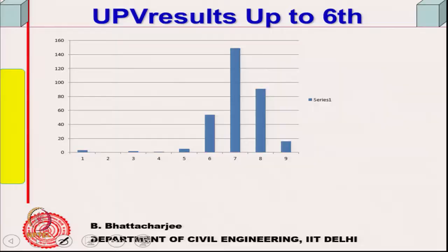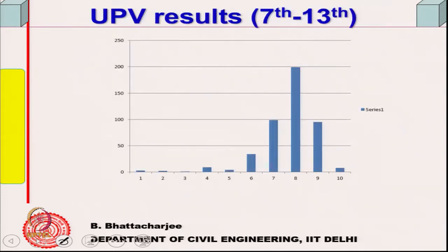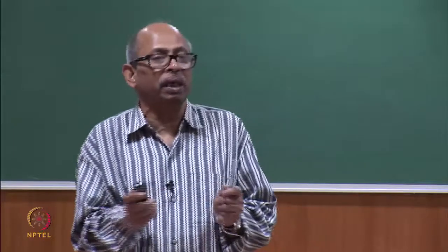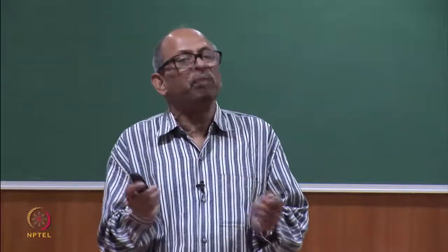So, you see this same up to the 6th floor, it was uniform concrete, but there is some bad concrete down there. So, it is skewed; there was some bad concrete, but not many. For floors 7 to 34 it was still increasing on this side, the ultrasonic pulse velocity result. I am plotting the histogram and this histogram did not match with each other. Initially when we plotted we found different peaks.